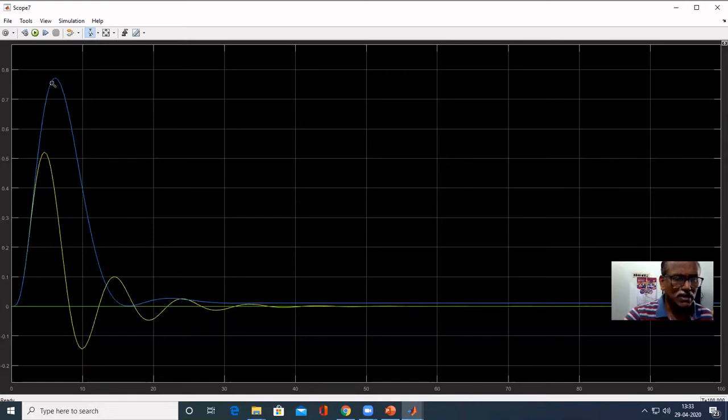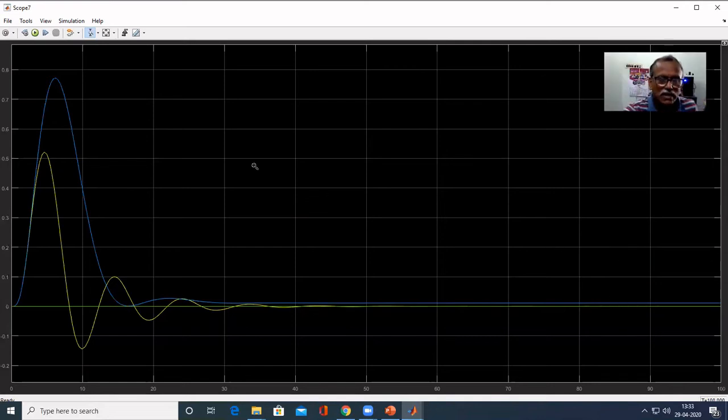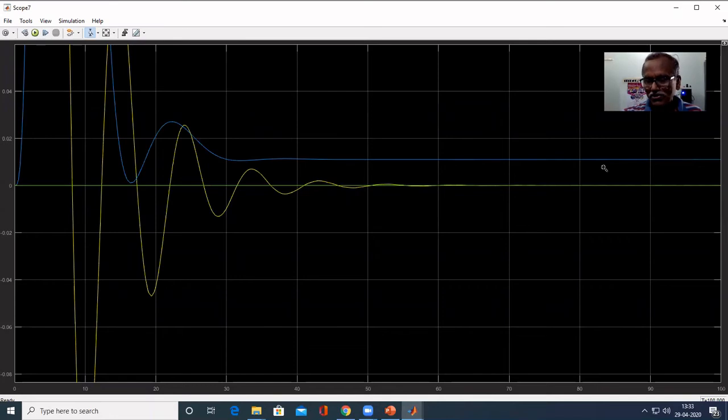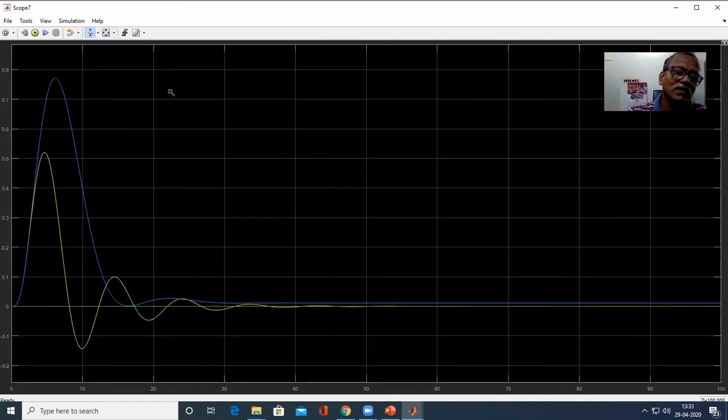But anyhow, it doesn't have any oscillations like deadbeat controller. You see here, one more thing we have to see here. It also has steady state error. And the Dahlin's controller has steady state error. Notice that deadbeat doesn't have that much oscillation here for load changes, as we have seen in servo response.